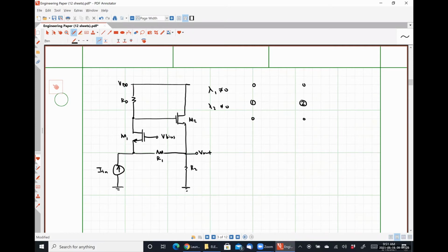Okay, so there are really two different ways that we can look at this, and in the grand scheme of things, it's going to make no difference whatsoever. One way to look at things, we know that this is always going to be connected because this is effectively our ground node, or our reference for everything. So one way that we can look at this is that our feedback network is literally just the resistor R1.